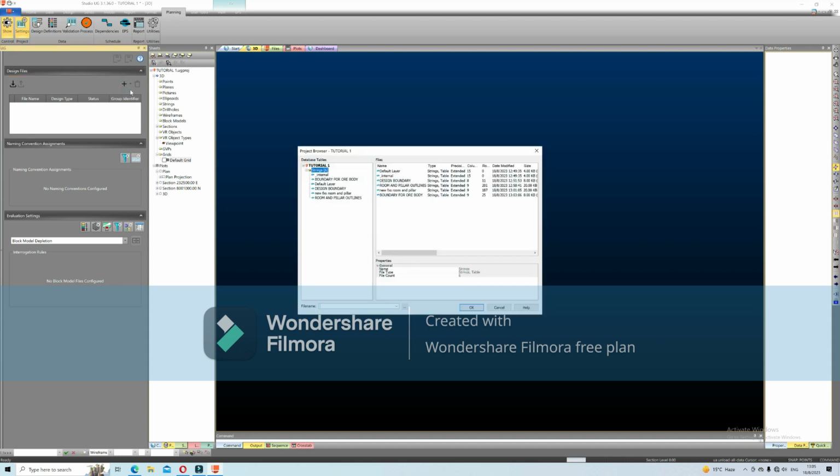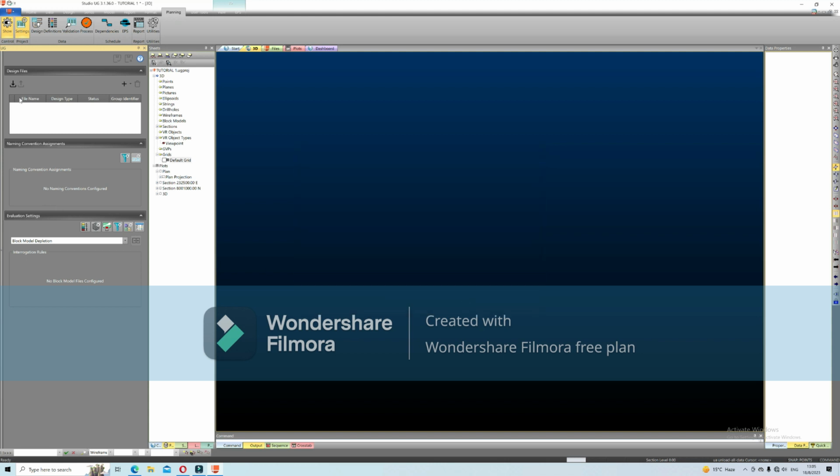A fixed cross section file, that means an FXS file that we have created. Those strings that we created that mark the outline of our design for the Roman pillar are called the FXS files. So I will just select the FXS file for the Roman pillar. This one, new Roman pillar FXS file. And I have clicked it. It has been loaded.